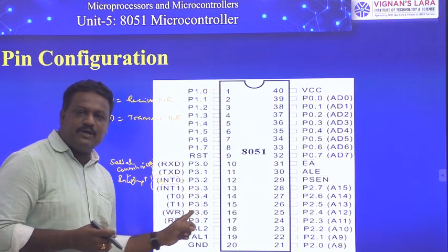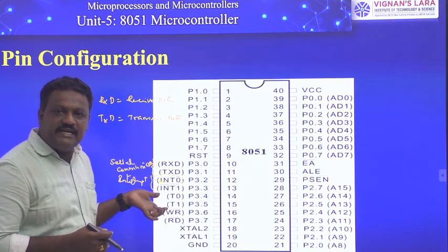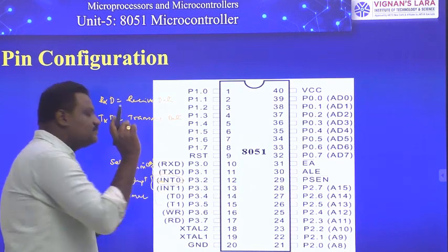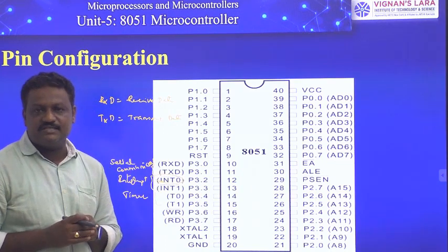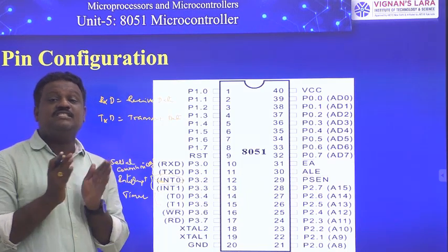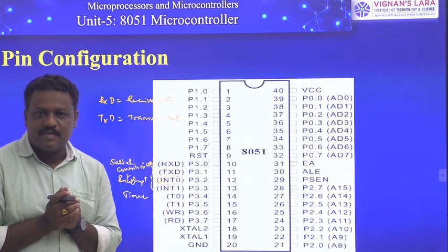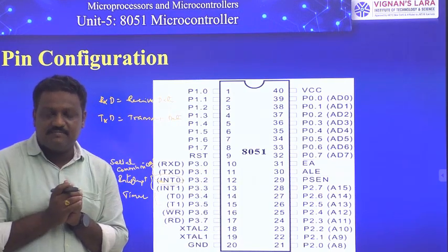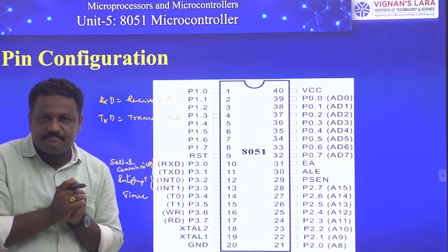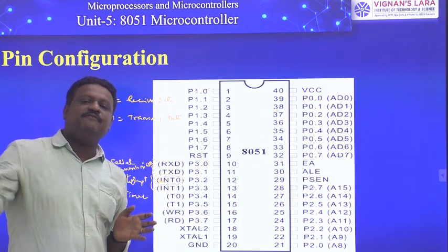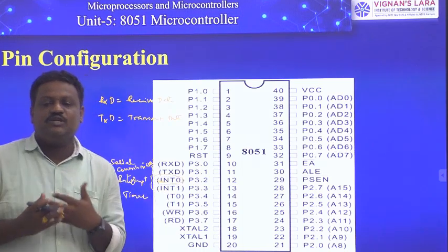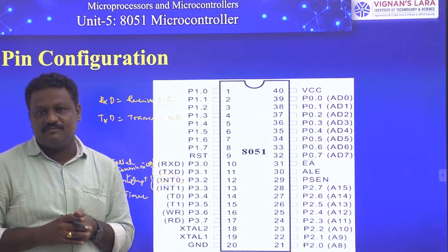Next two signals, that is P3.4 and P3.5, we consider as T0 and T1 in expanded mode. These two are timer related signals. Again, we remember friends the features of 8051. It has two 16-bit timer/counter circuits. When those circuits act as counters, they need a clock pulse from external devices to count. When your controller receives a clock signal from external devices with the help of T0 and T1, your internal circuits will act as event counters.